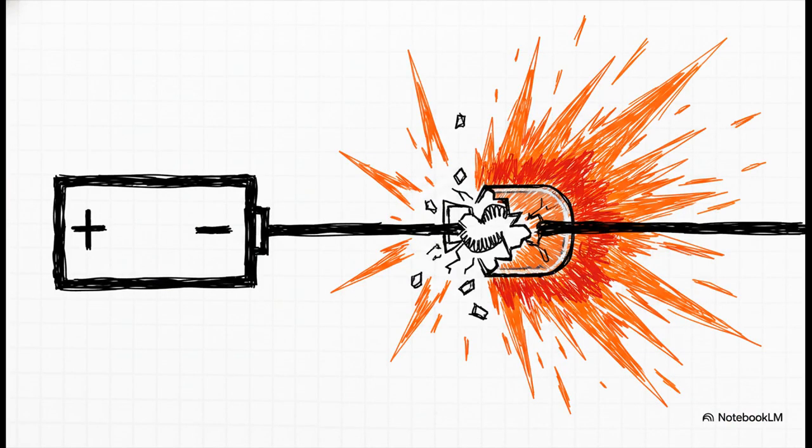Well, the answer is very bad, because an active semiconductor diode displays minimal internal forward resistance once you cross its voltage threshold. Failing to install a current-limiting resistor results in a direct short-circuit loop condition. Without any resistance to throttle the flow, the circuit enters instantaneous thermal runaway. The current spikes massively, and you will literally vaporize the microscopic internal wire bonds inside the LED casing. It will pop, and it's ruined forever.